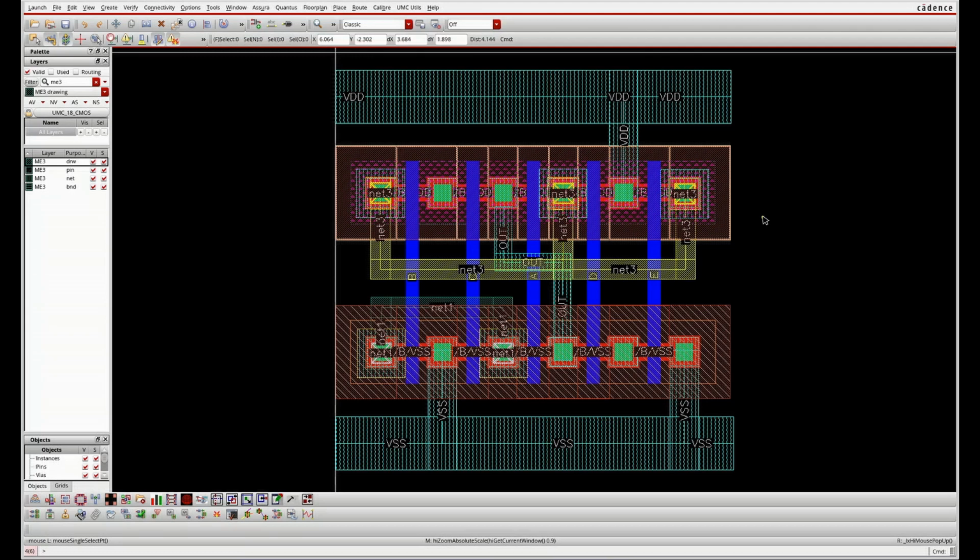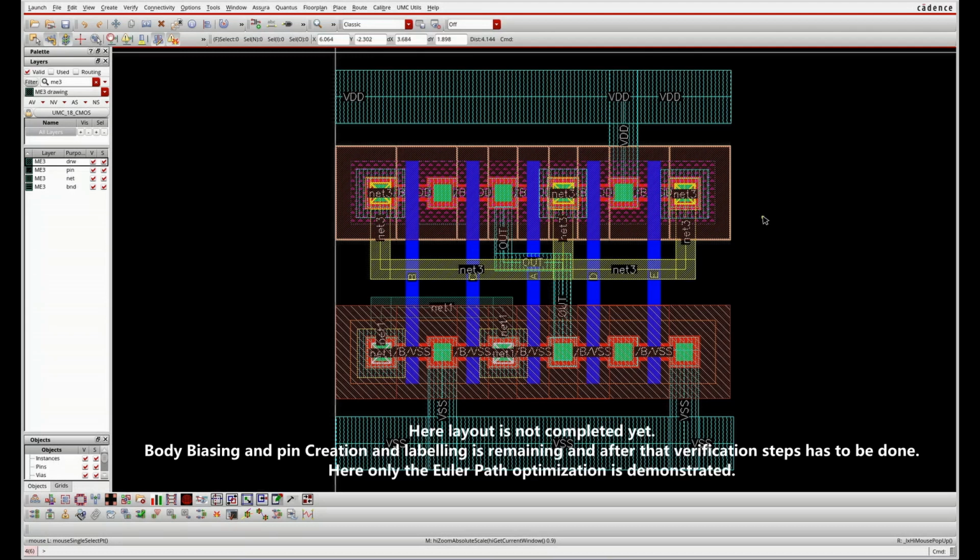I picked a value from the PDK, that is SCL 180. Depending upon the PDK, here I am using the UMC, but I don't have the values of UMC 180 standard cell height. So I am using the SCL 180 nanometer standard cell height, that's 5.6. So depending upon your PDK, you can use your standard cell height and maintain it accordingly.